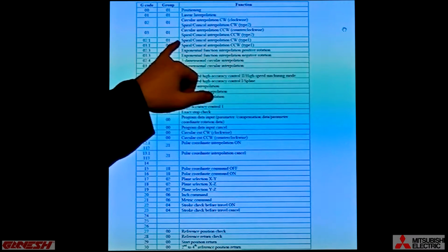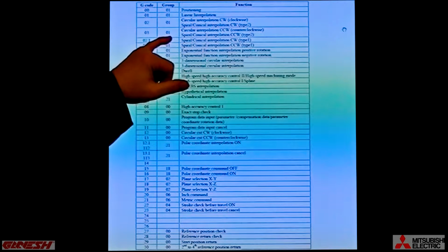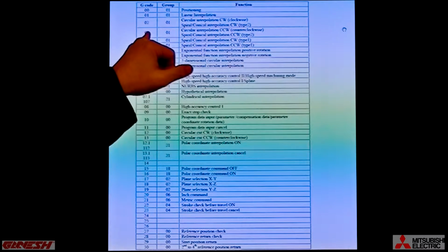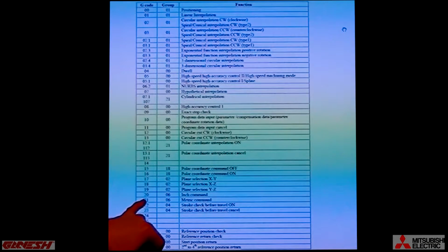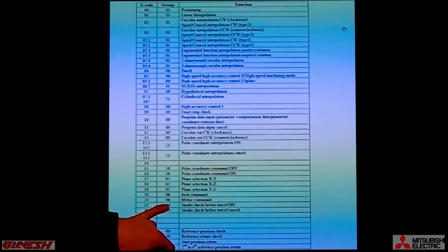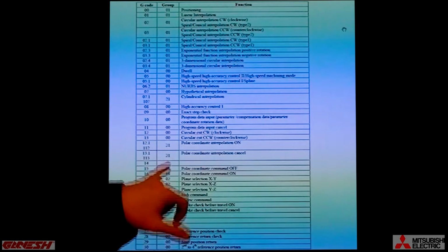So here is an example of modal group 1 G-codes. G00, G01, 02, and 03. You're familiar with all of those. We've just worked with those extensively. And they're in group 1, so a G01 would override any one of these: 03, 02, and 00. But a G01 will not change the modality of a G20, for example. The only thing that will take a G20 out of inch mode is a G21 metric command, because they're in the same modal group. Okay? Because they're in modal group 6, they override each other, but they have no effect, nor does that G-code affect any other modal group.